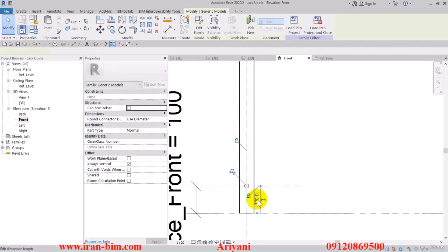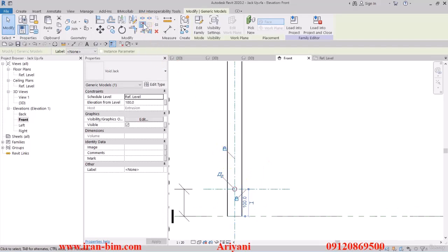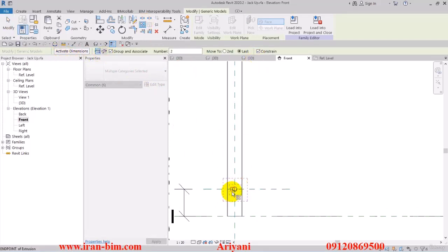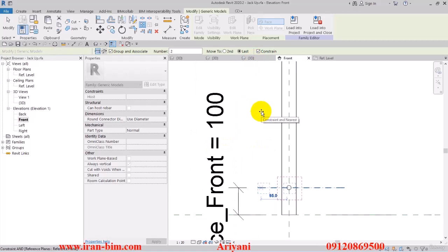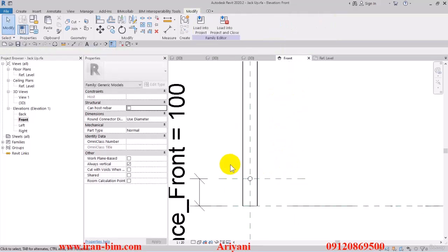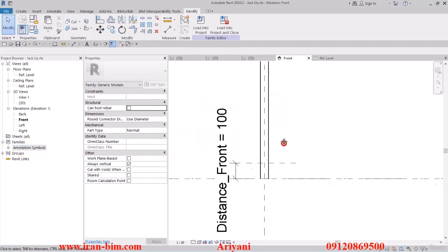So now I'll select this, although there is an issue in this part. Let's see if I've guessed correctly or not. We'll go here, and yes. Because the surface that we've selected as our host is circle-like, this cannot be drawn in the up or Z direction. And so the method that we've chosen for the void here is wrong. So I'll delete this. From here, click yes.